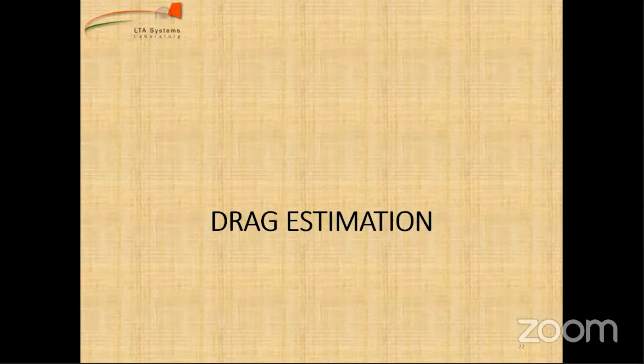By knowing velocity. You need the drag coefficient, right? How did you get the drag coefficient? D upon half rho V square S, with the help of the drag formula. No, that's what I'm saying to you. To estimate the drag coefficient, you need to first measure the drag. If you know how to measure the drag, then there's no need for this. See, there's a contradictory statement. So how do you do this?